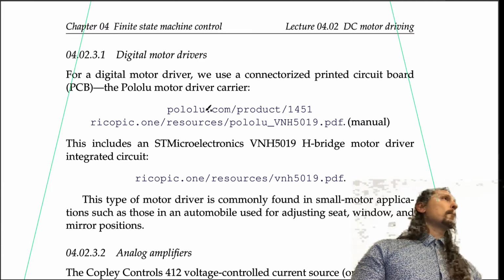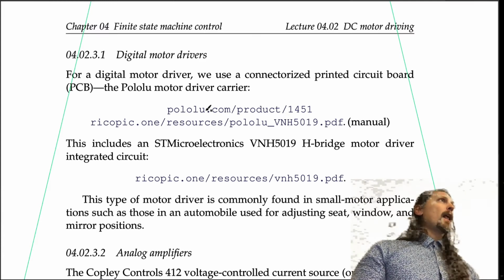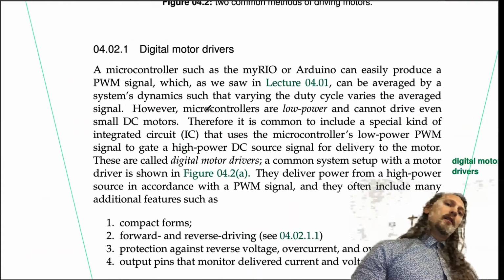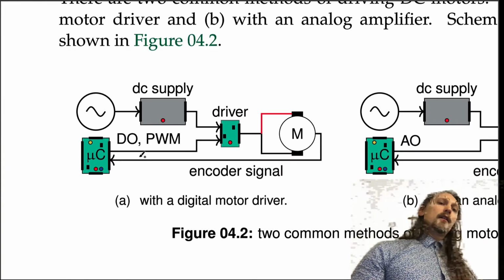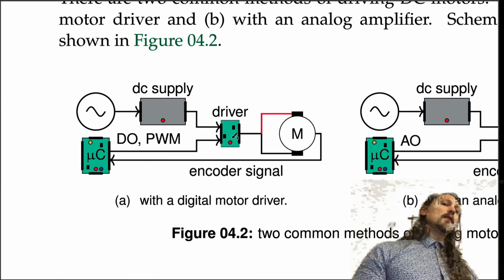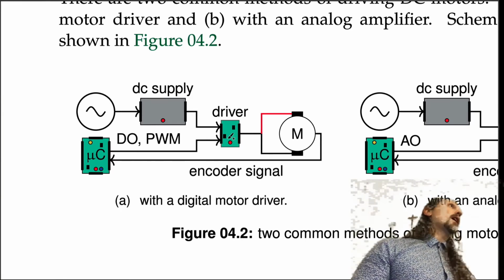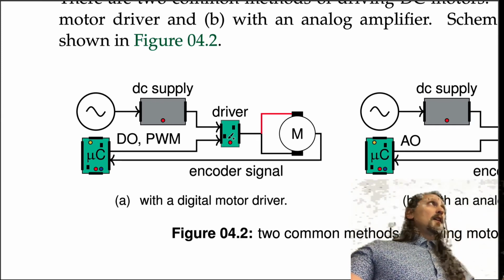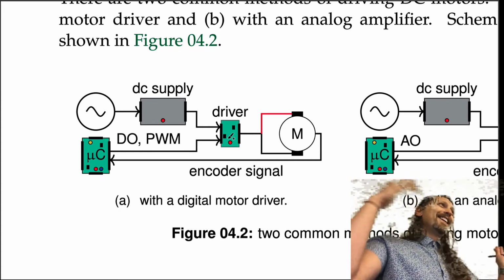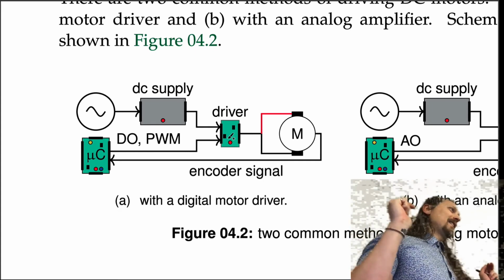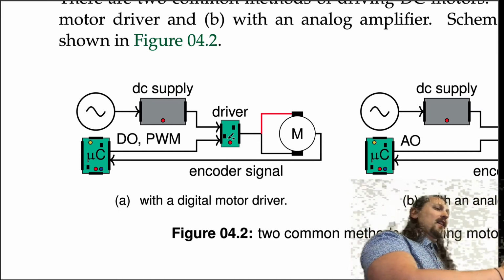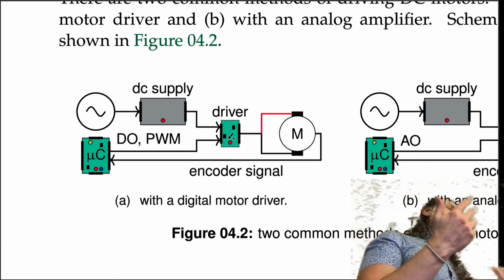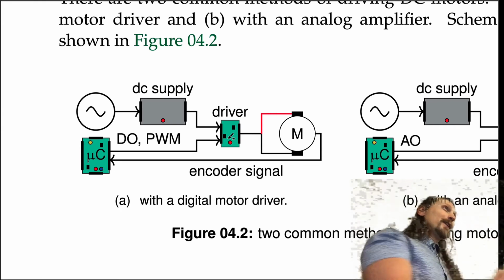So yeah. So you can just drive the motor without a microcontroller? No, you need the microcontroller because you need to have the microcontroller PWM signal to tell the driver what to do. So the driver is just saying, I'm a little gate and tell me when to open. Like it's essentially doing that. So it's like the gate that lets through a lot of power and closes the gate, and it pays attention to somebody, the microcontroller, telling it open, close, open, close.